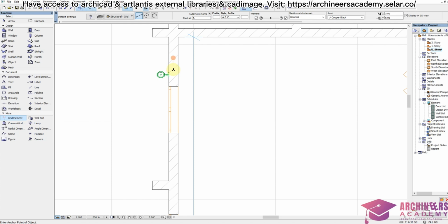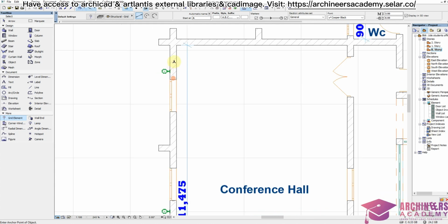As we all know, the center of the walls are mostly common. They are mostly used in design. You can still work with any of them. It does not affect the setting out process. The builder will just have to follow the pattern you use. But for generality's sake, I'm going to place my grid at the center of the walls.